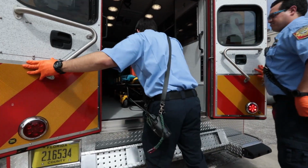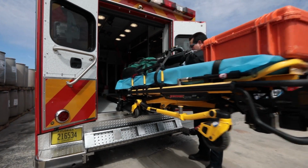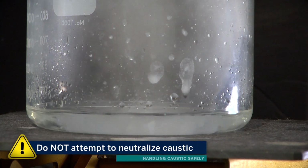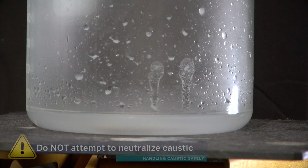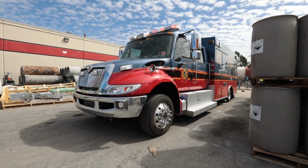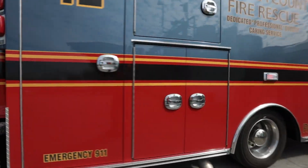When personnel have been exposed to caustic solutions, additional medical treatment may be necessary. Never attempt to neutralize the caustic. Neutralization is an exothermic reaction that produces heat and can cause thermal burns as well as chemical burns. Do not apply oils or ointments to burns without specific instructions from medical personnel. When necessary, the victim should be moved to a medical facility immediately following prescribed washing.